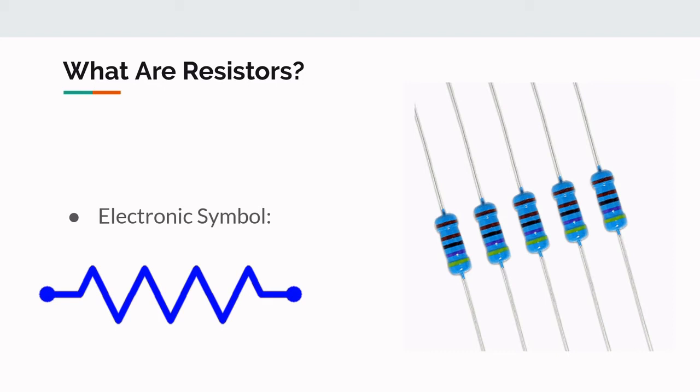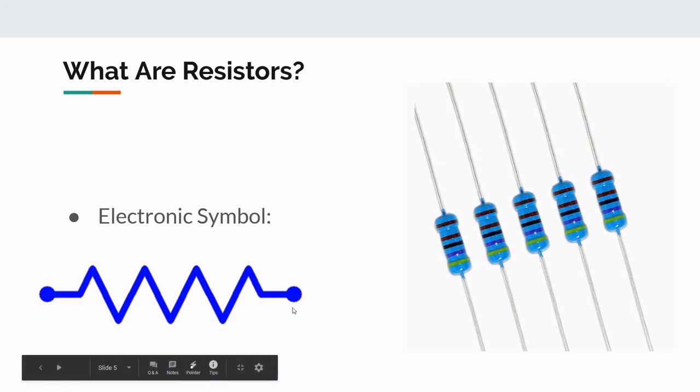In smaller value resistors designed for lower power circuits, the copper winding is replaced with a spiral pattern of carbon. Resistors like this are much cheaper to make and called carbon film. Generally, wire-wound resistors are more precise and stable at higher operating temperatures. The electronic symbol for the resistor is shown below. They do not have an anode and cathode side and can be interchanged.